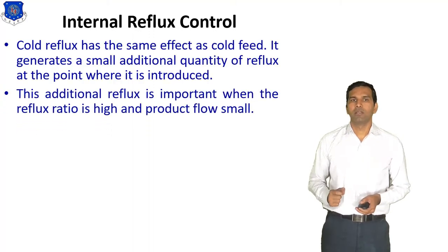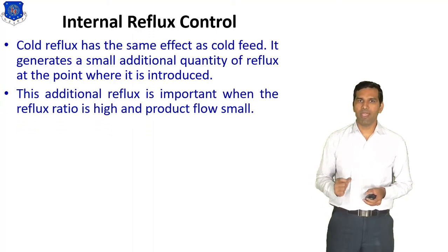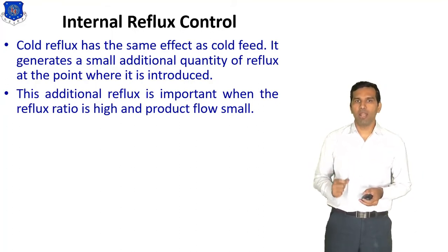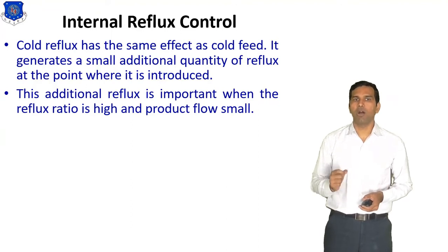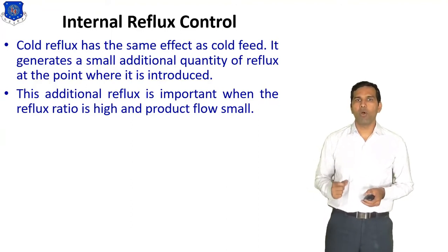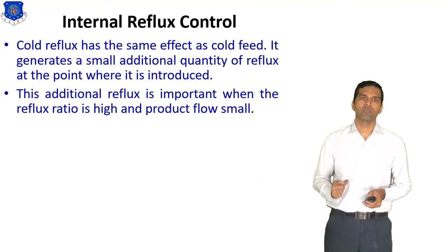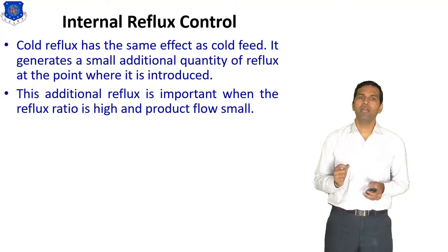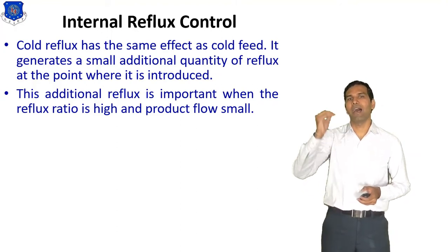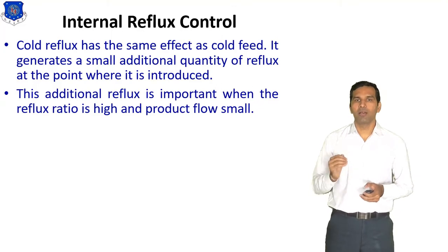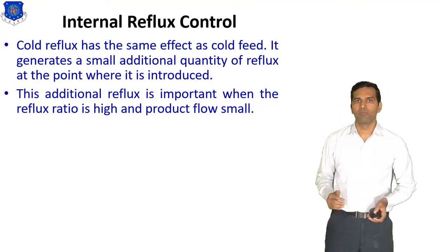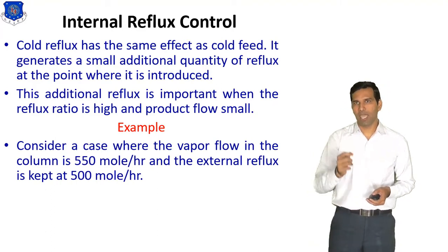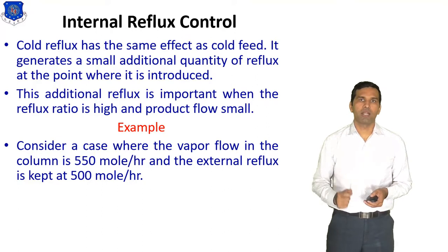Cold reflux has the same effect as the cold feed. It generates a small additional quantity of reflux at the point when it is introduced. This additional reflux is important when the reflux ratio is high and product flow is small. Now we understand this sentence with the help of this example, so we get better understanding.